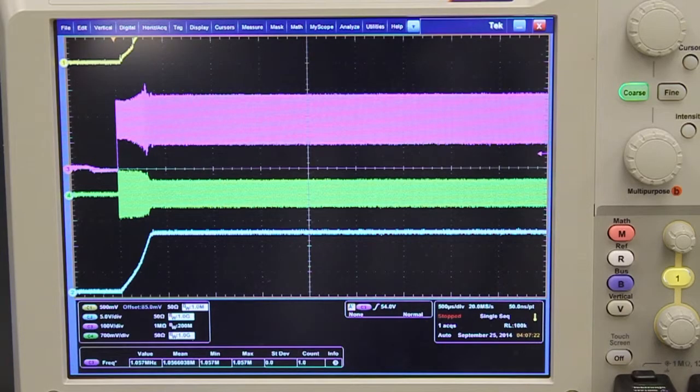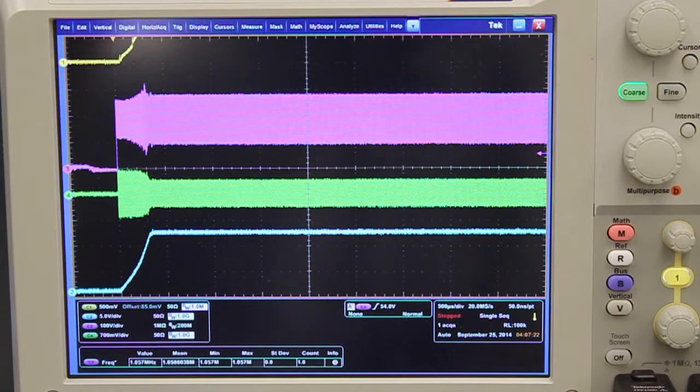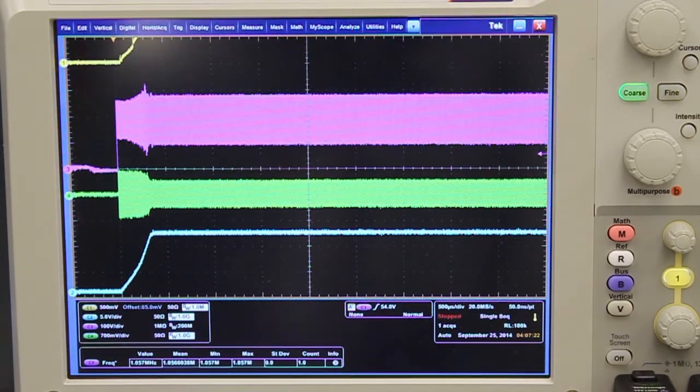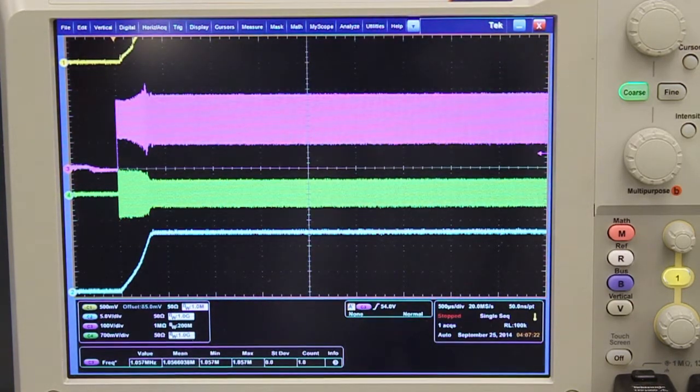This is a soft startup waveform under 0.175 ohm load condition. From top to bottom, the waveforms are resonant voltage, resonant current, and output voltage. The startup process is very fast, and the maximum stress is below 1.5 times full load stress.